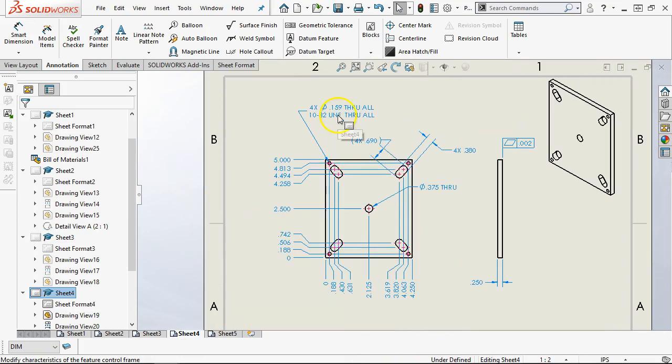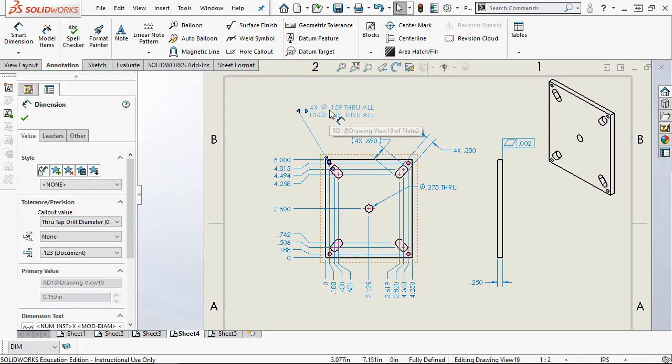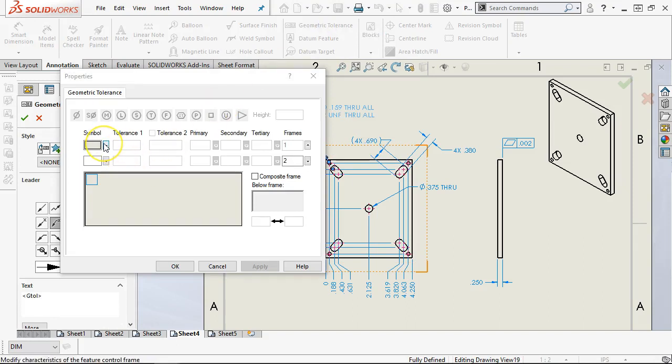All right, so in the process of doing all this, I am going to go back and verify that I built these up correctly. And so the geometric tolerance applied to this one will basically be the same, right? They're going to be able to move in the same direction. So a positional tolerance, 10 thousandths, with a primary A, or C, I'm already shifting, D, and E.